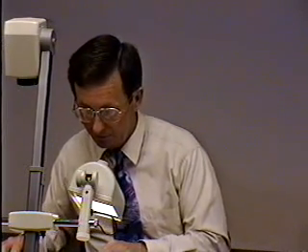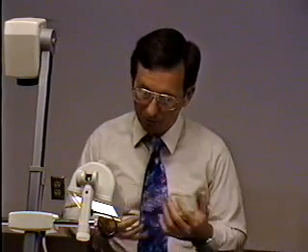And I'll speed up just a bit. We do have quite a few topics here, but conservation of momentum is quite useful in dealing with hydraulic jumps, because what happens in hydraulic jumps is you've got such turbulence, there's such a high amount of energy loss that it's quite obvious you can't use Manning's equation to estimate energy loss. You don't have anything to estimate energy loss. And so we're not going to try to estimate energy loss. Instead of conserving energy and looking at energy terms, we're going to work in terms of a conservation of momentum.